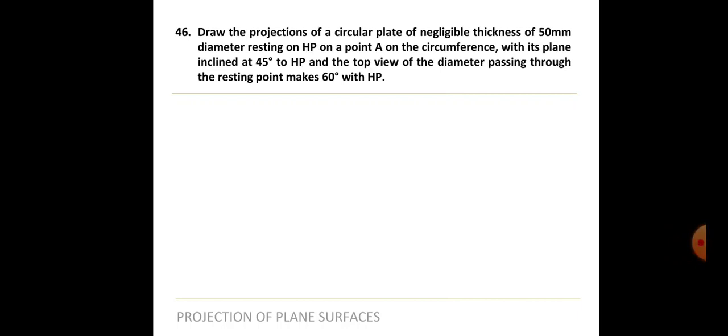Okay, not HP, VP. So first of all, when the question is given, you need to understand from where to start this particular problem, whether the lamina is resting on HP or resting on VP. So in the question, it's very clearly stated that the lamina is resting on HP. That means you will start your drawing below the XY line, that is from the top view.